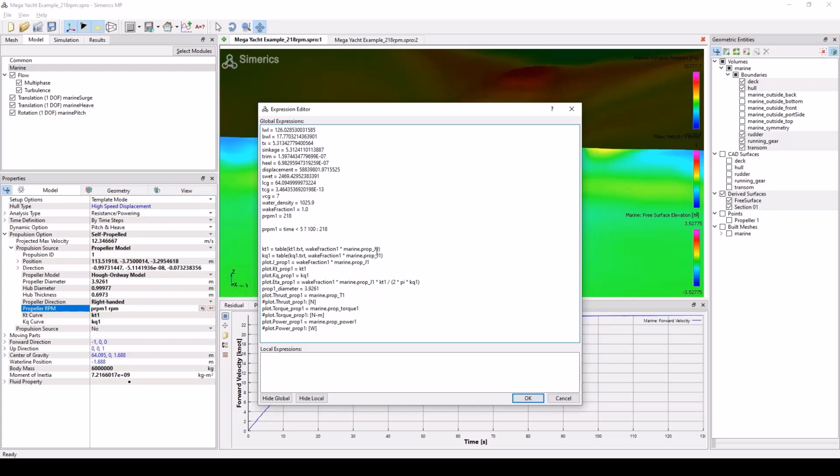That's just an example of an expression. And so it would use that in here. Now, if you want to leave an expression in there because you might want to use it in the future, but you don't want it to be active right now, you just put a pound sign ahead of it. The pound sign or hashtag is the symbol that means these are comments. These are commented out. Don't use them. They're not live. I'm leaving them there for reference. So you can use that also for making comments, like, below is the expression for a variable RPM. As soon as the interpreter of this expression editor sees the pound sign, it just ignores anything else on the line. So right now everything's still the same as it was before. I just added some information.